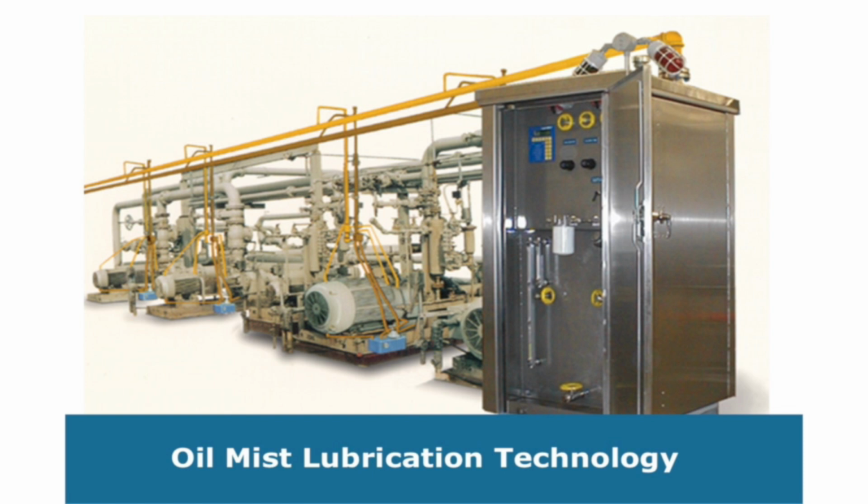general really relates to. We can see here a cabinet. It's on the right side. Inside this cabinet, and the door is open right now, we have an oil mist generator, and we have also a small container in which the bulk oil is contained. There are pipes that you see on top. We would normally call these pipes a header. And one of these headers is feeding the oil mist towards the machines that are being oil mist lubricated.